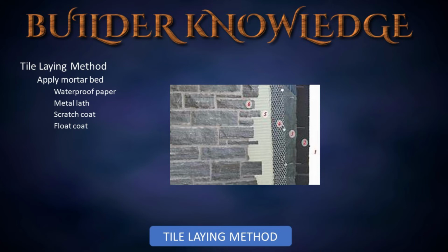Apply float coat. This coat is also called the leveling coat and also the brown coat. But we will be referring to it as the float coat from this point. Mix float coat to a 1:1:3½ parts cement, hydrated lime, and sand. Bring flush with screens or temporary guide strips placed to give a true and even surface at the proper distance from the finished face of the tile.